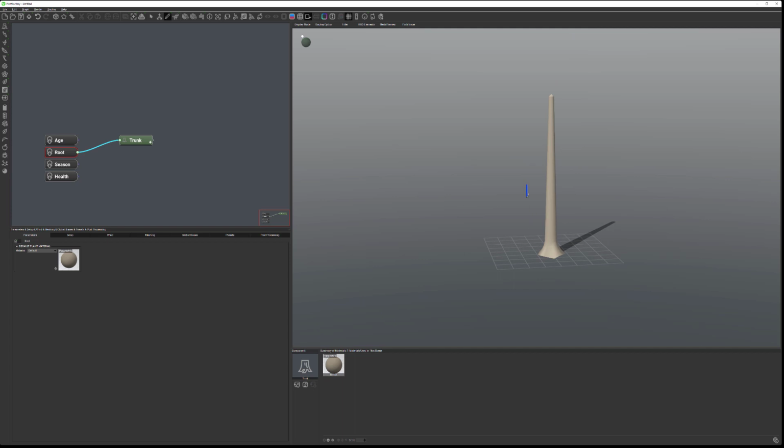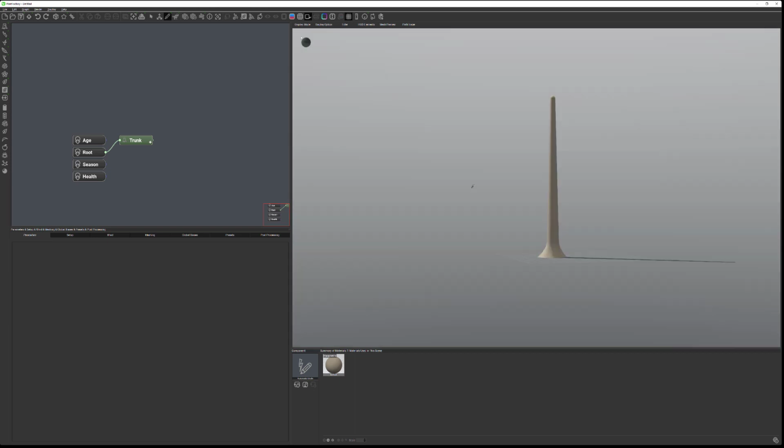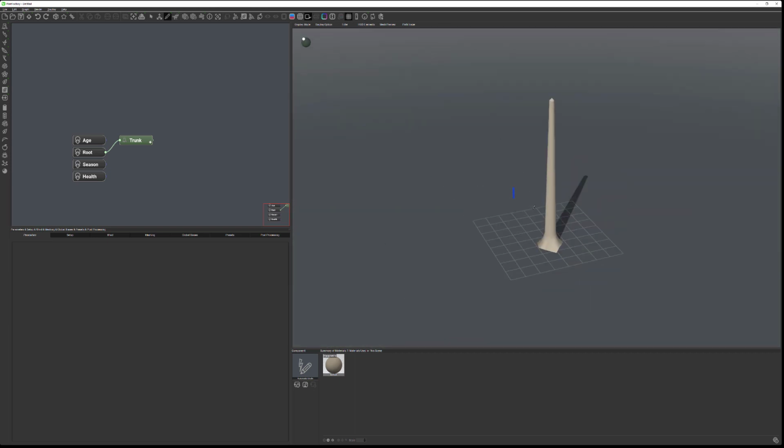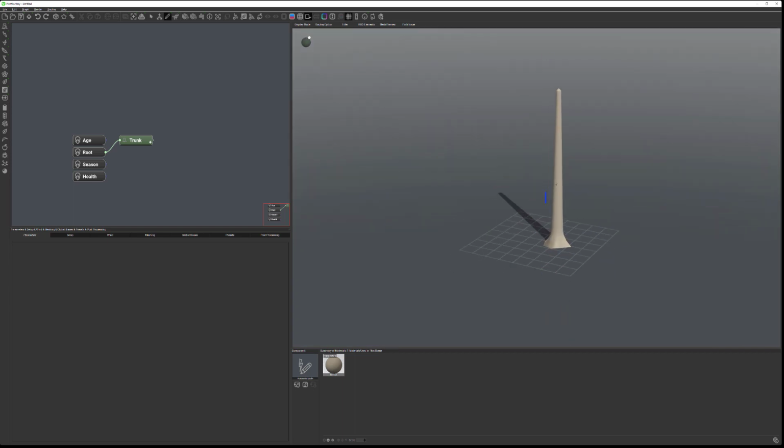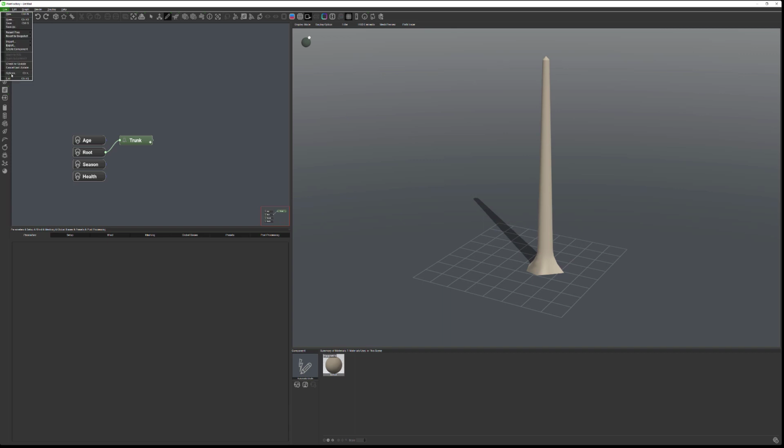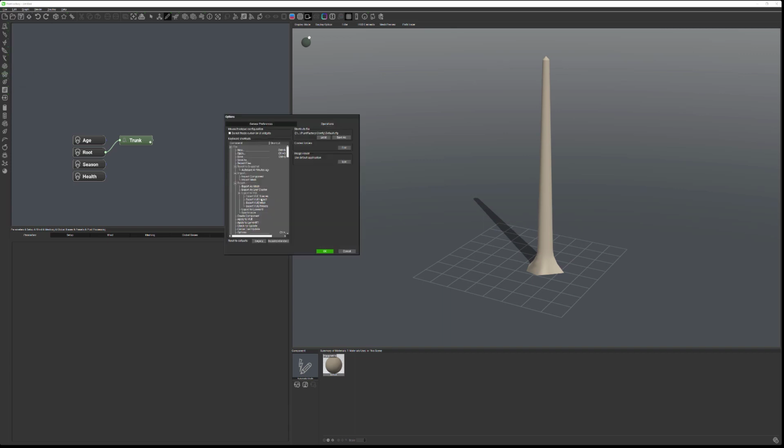And by the way, inside you can hold down the Alt key, and your left key will turn around, like orbiting around. Your middle key will be panning, and your right key is zooming. So it's a very standard preset. And of course, any of those keys you can change by going File, Options, and inside here you can change them as you need in the Operation tab.